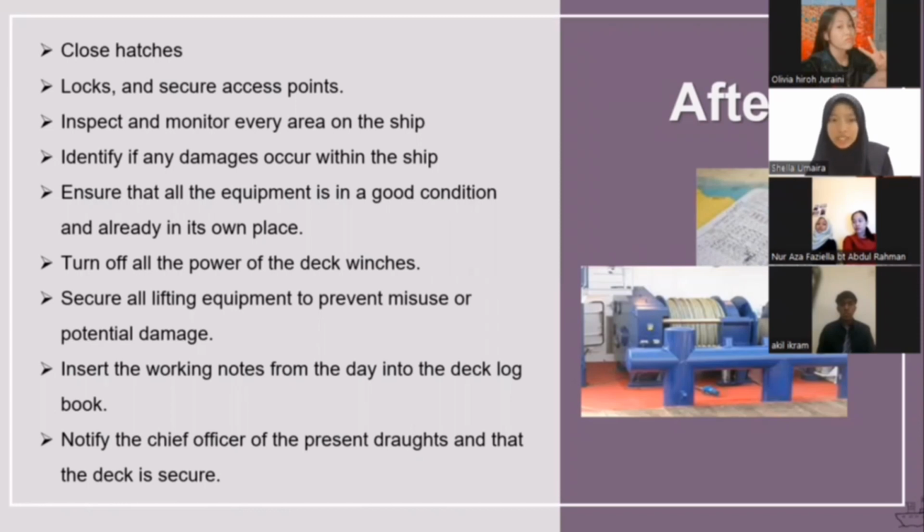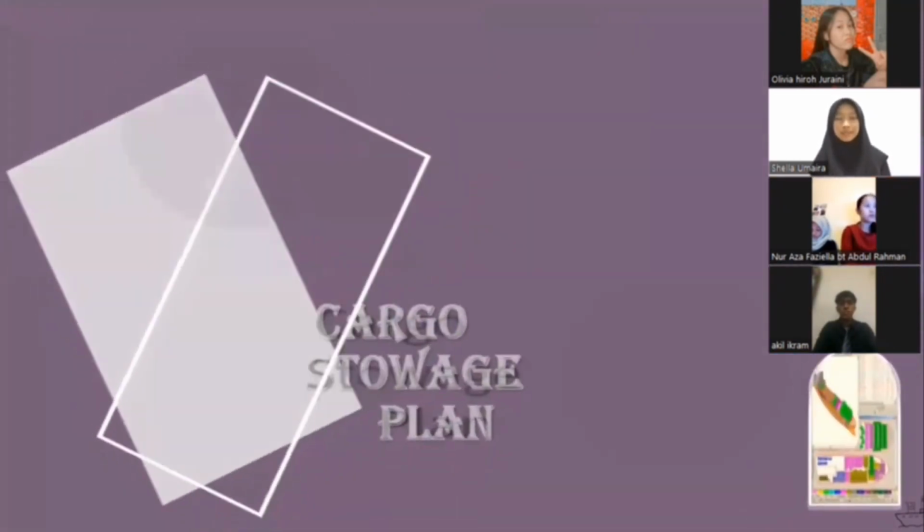After that, insert the working hours from the deck into the deck logbook. The deck logbook is the second picture behind the deck winches. And lastly, notify the chief officer of the present draughts and that the deck is secure for other cargo operations. That's all. Next presenter.